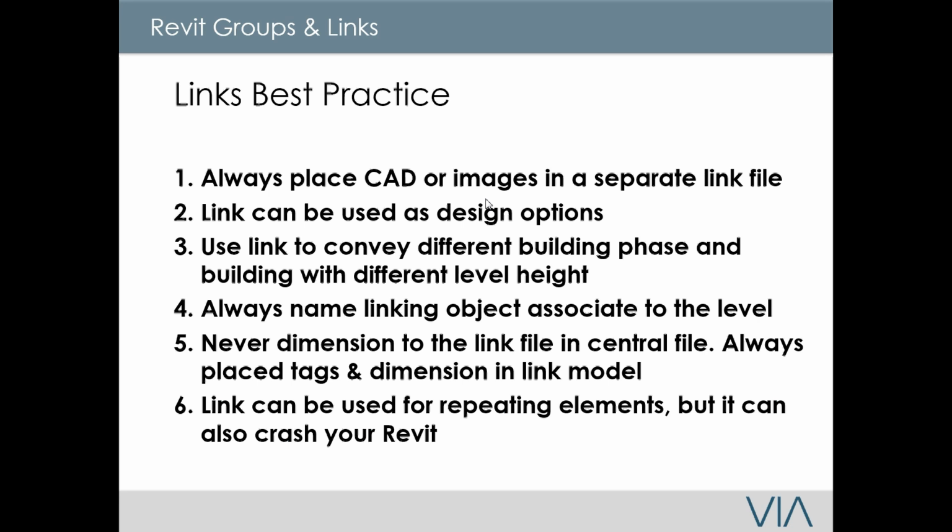The next one is to never dimension to a link file in the central file. Always place the tags and dimensions in the link model. What I mean by this, as I spoke about earlier, is that if you do any dimensioning in the central file and then you dimension to a link file, you hope and pray that people will not unload your links. Okay, it can happen.